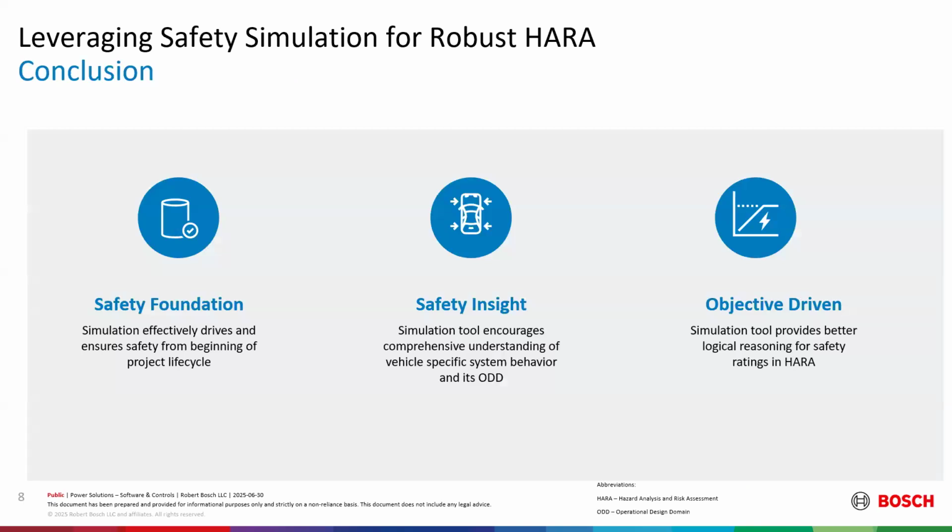So what is safety simulation doing here? It lays a strong safety foundation right from the beginning of the project. Right when I don't have a prototype or I cannot test it in the field, I can start using a model-based approach to come up with realistic figures for my safety concepts. Then I can have safety insight for the intended vehicle for the intended ODD. Also, I can make this entire HARA objective driven rather than subjective, where I can derive the characteristics for my particular vehicle parameters.